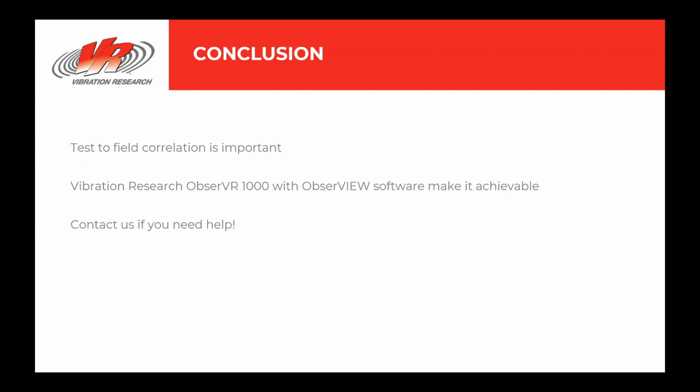And finally, if you're going to run this test, make sure that you get a really good profile using these tools and what we learned in this webinar, but make sure that you're using the right test equipment, that you have a good fixture, that you have good control, and you understand what your failure criteria are before you begin testing, and you execute your test.